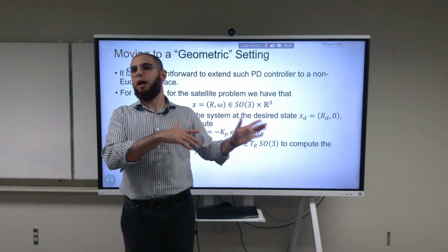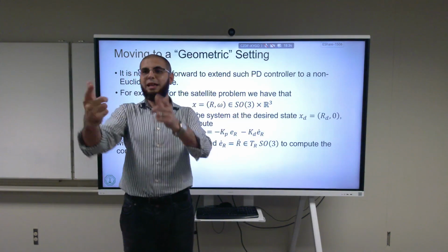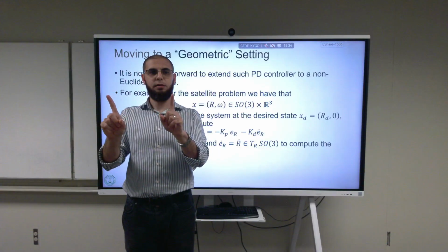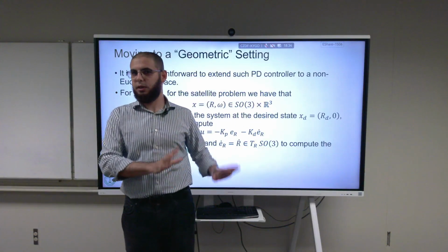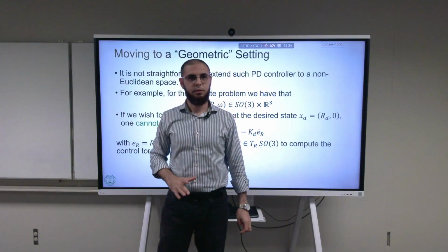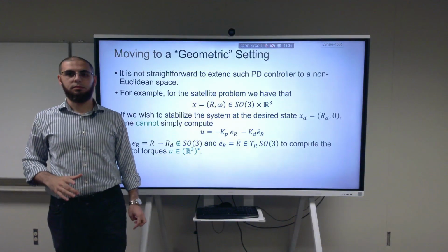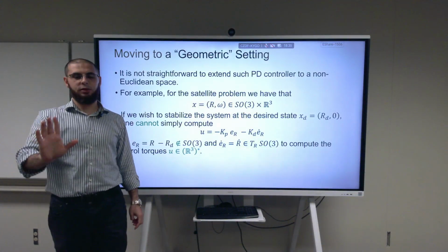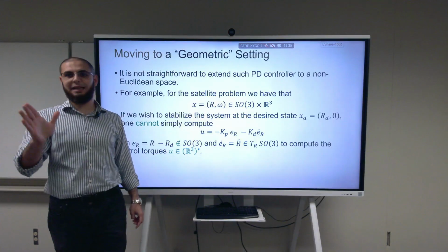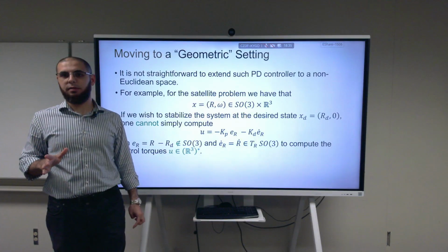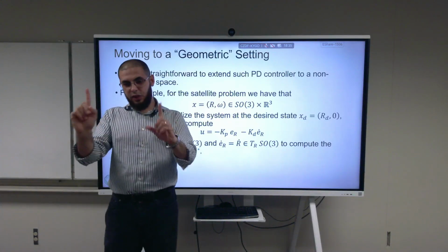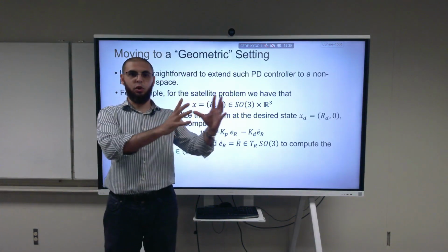You have another problem now, which is how do you convert this wrench to the individual thrusts of the propellers? This is called the control allocation problem. That's another story. Do the reverse of what we did in the project, of converting the wrenches of propellers to... Absolutely. Excellent point, Norman. That's exactly what you did, the opposite of what you did in the assignment. The assignment was individual wrenches, convert them to the total one.